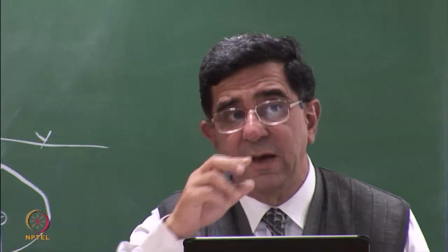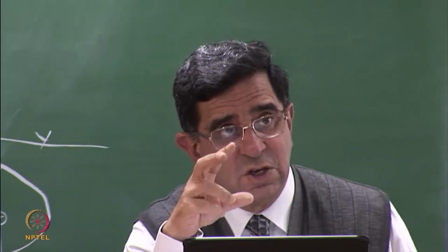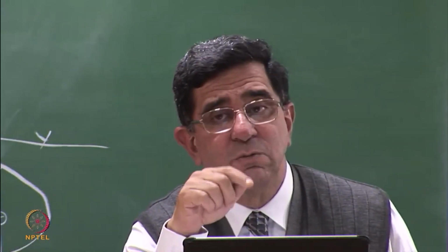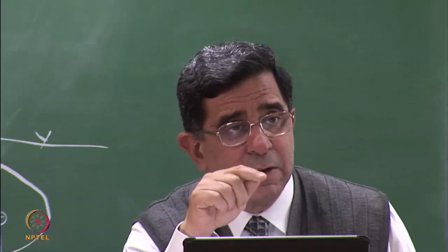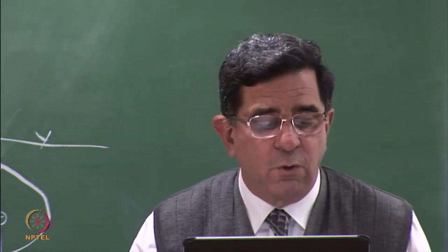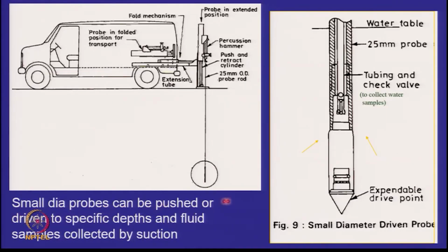You are not bothered here about whether you are destroying the structure of the soil, whether the strength has changed, whether you are getting an undisturbed sample. No. What are you bothered about? You would be able to reach a particular depth and pick up the liquid sample or the gaseous sample by suction. So for small depths, we have special probes which can be pushed or driven into the ground to collect the samples by suction.